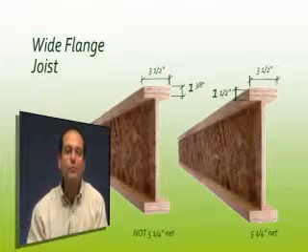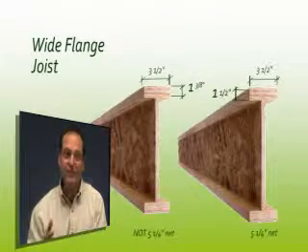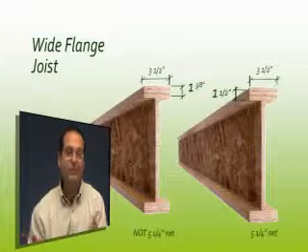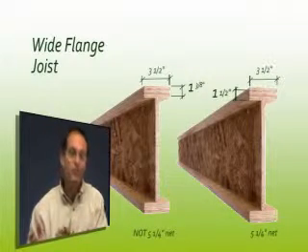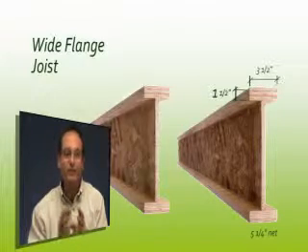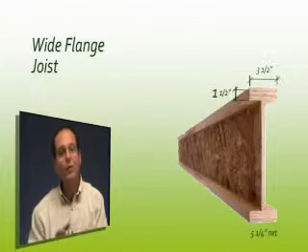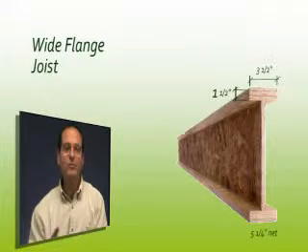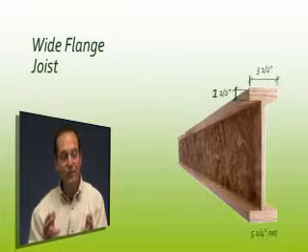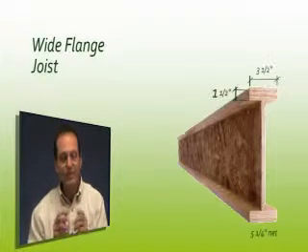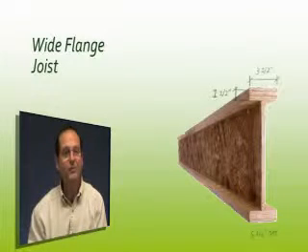The engineered wood industry is a very competitive industry. Flange thicknesses have been dropping for the last 5 to 10 years. So for the most competitive joists, those are out there. However, most manufacturers still maintain an inventory and continue to manufacture the full 1.5 inch thickness joist just for this reason, because there will be fire assemblies, it does need to be done, and that's the one that actually makes it work. So make sure that's the part of the specification.